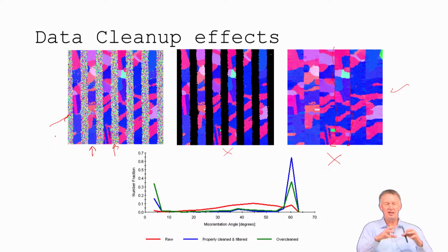So you say grain dilation. So it effectively takes each one of your grains and it increases the border by one step size in your scan. So it just dilates it out, right? So each grain grows by one dimension around the outside. It doesn't grow into other grains, right? It stops, it doesn't grow. If a grain isn't defined in a region, then the grain will grow into that.